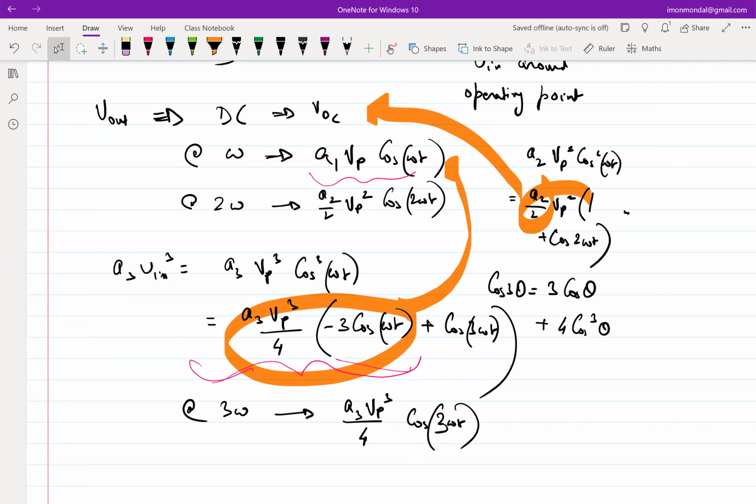What we are saying is that I have a sinusoidal input. I pass it through a nonlinearity. It is going to create a fundamental at omega, which I want. But the 2 omega looks like it is out of band. It's going to 2 gig, where I do not have any activity. I have a narrowband filter, an LC filter, which is going to filter it out. So then should we care or should we not care? We should care, because while doing this analysis, I assumed that I have a single tone. That did not necessarily need to be the case.